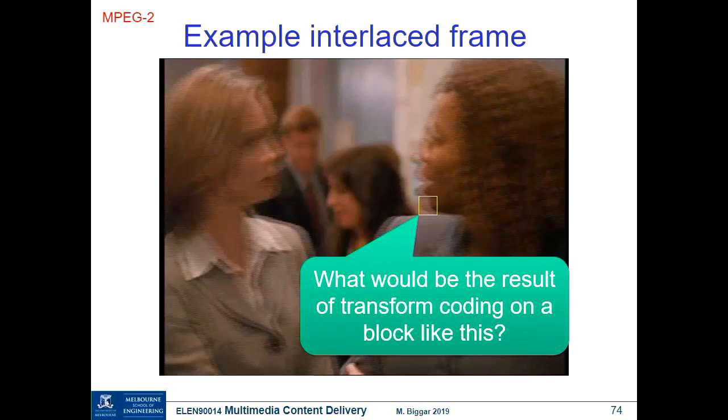We assume that most pictures have intensities or colours that change only gradually across the frame, right? So if the luminance or the chrominance signal changes only gradually, then it's composed of only low frequencies. And so when we go to the transform domain, our high frequencies will only have very small magnitudes and we can throw them away. That's the short version of what transform coding is all about.